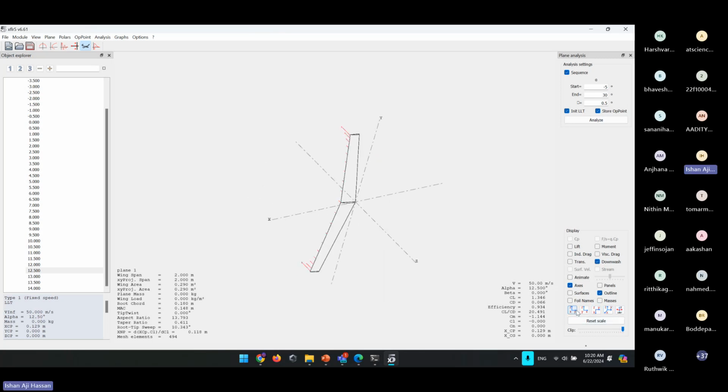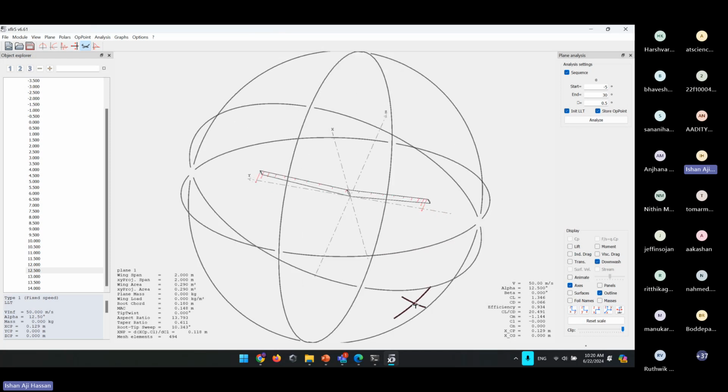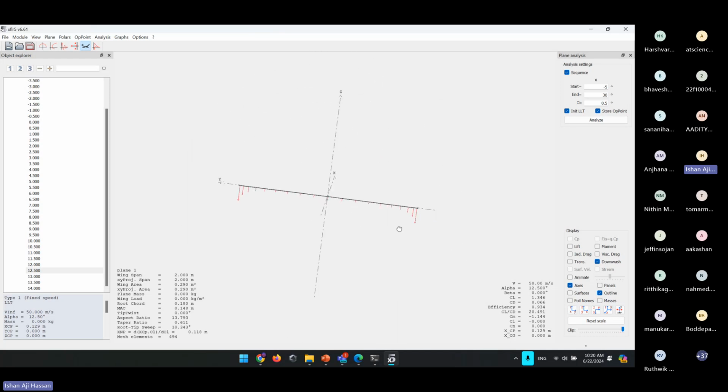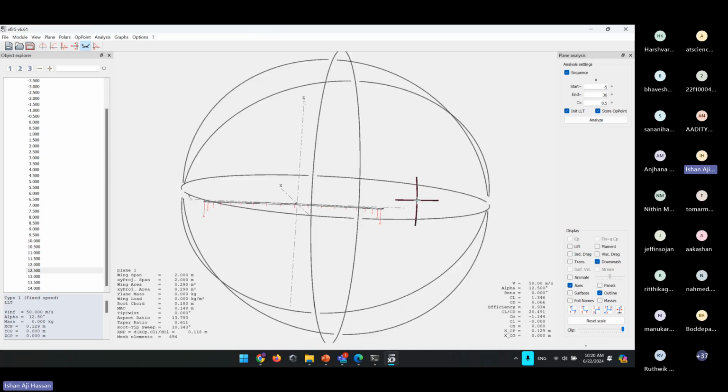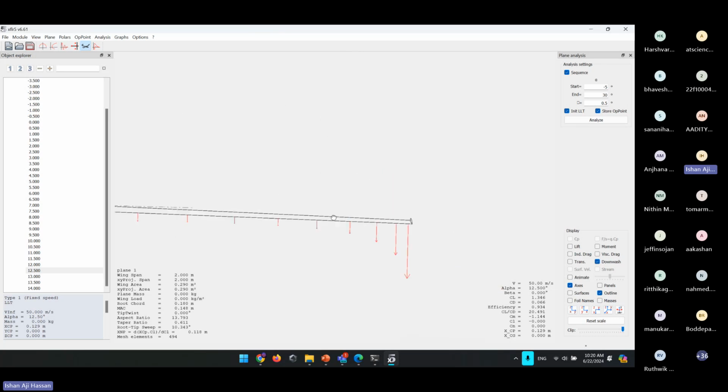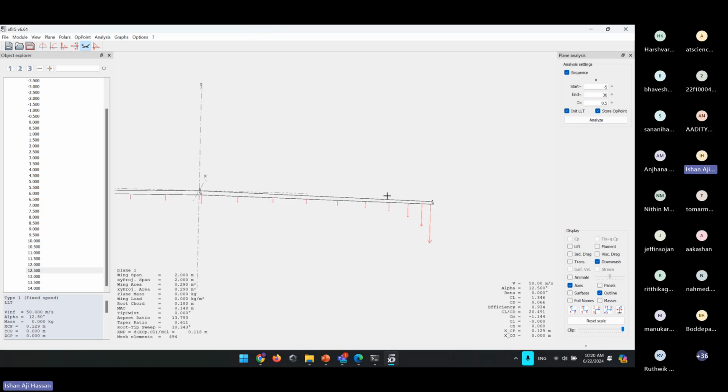So I'm just going to be using the forward view. This is looking straight ahead. So the wingtip vortices basically act at a very high intensity towards the wingtips. And this means that since this vorticization happens, the airflow is basically in a... I'm looking at my right wingtip here. So here the vortex will be in a counterclockwise direction.